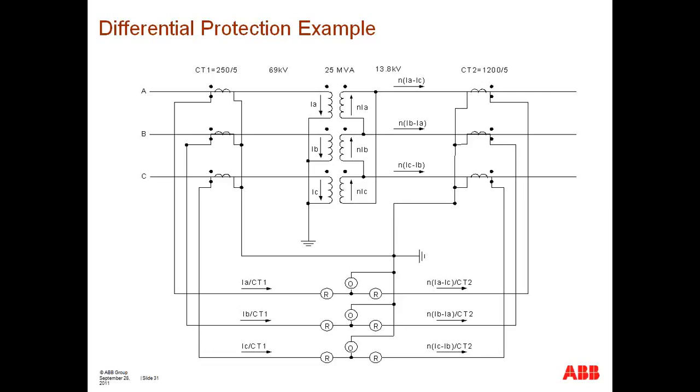Let's see, what else do we have? We have another question here, which again, back to the SPR, the sudden pressure relay. Can a large through-fault near the transformer shake the transformer enough to trigger a sudden pressure relay? Again, it's the sudden pressure relay. It's looking for a high rise of pressure within the tank of the transformer.